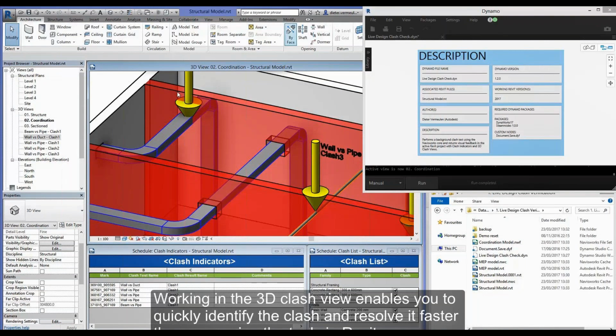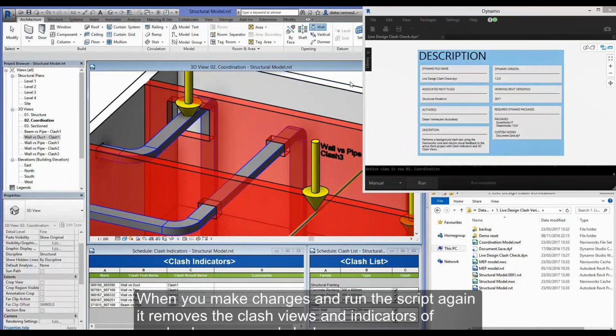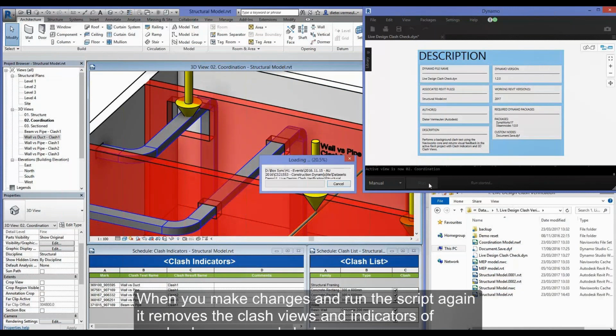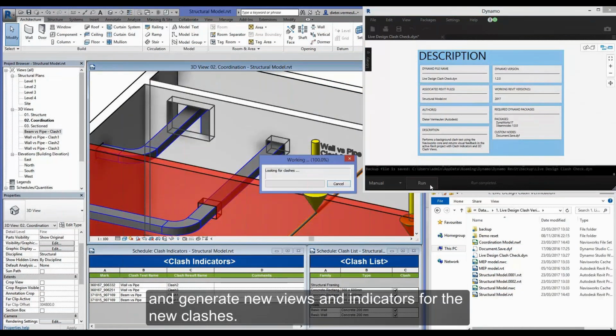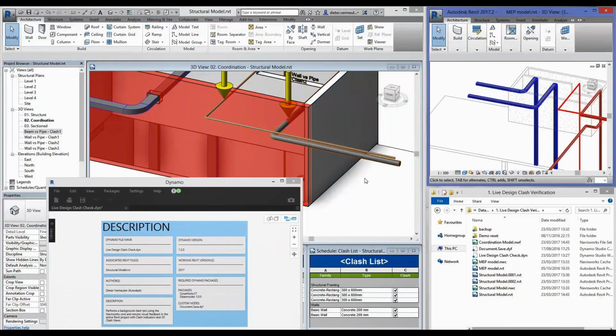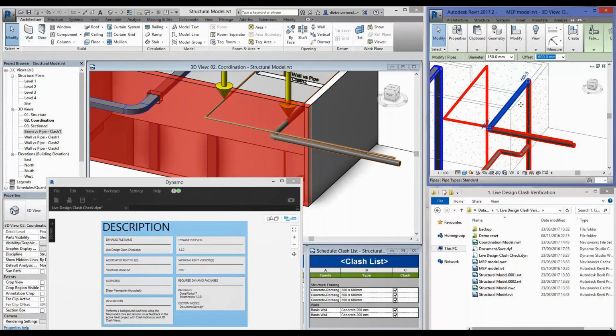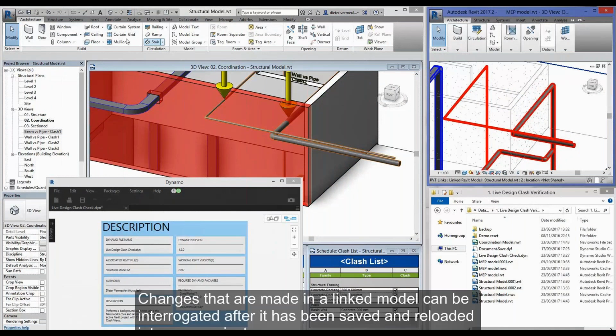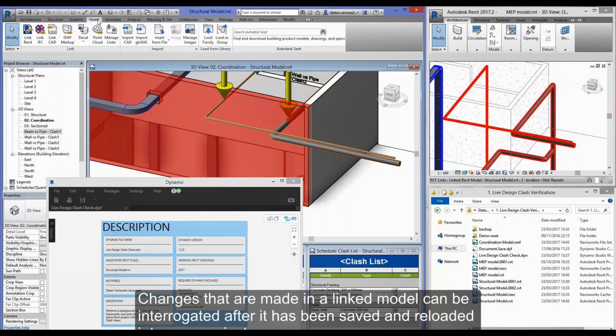So you'll also notice the walls in there are highlighted in red. Immediately, we can go back and start creating penetrations where we had clashes, rerun the clash, and immediately you'll see that the wall that didn't have any penetrations in it is now updated and it doesn't show highlighted in red anymore.